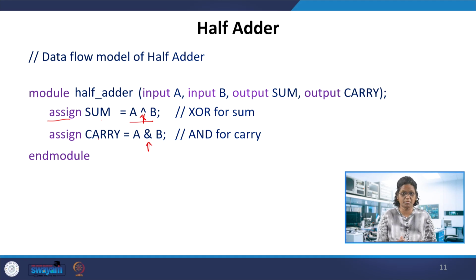So these assign statements are continuous statements, assign sum and carry. This is also a concurrent assignment or concurrent statements. It's not sequential statements here.